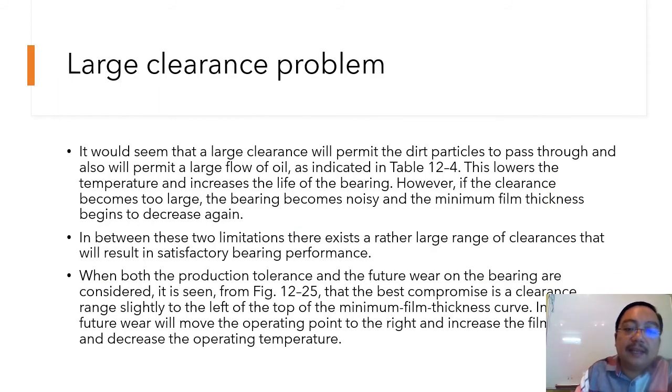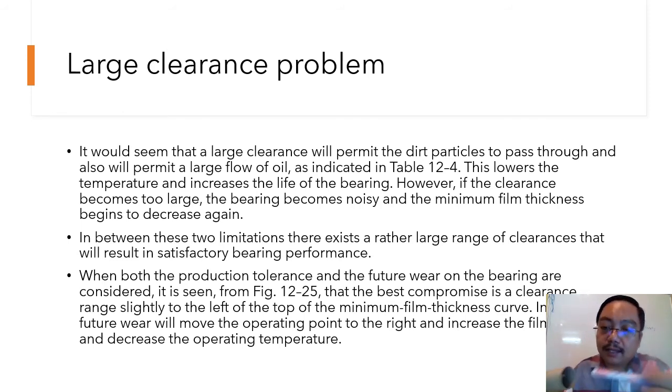And as I said, big clearance also gives a problem. Small clearance is also a problem. It seems that large clearance will permit particles to pass through and will permit large flow of oil, as indicated. Of course, lower the temperature, increase the life of the bearing. However, if clearance becomes too large, the bearing becomes noisy. This is logical because of the clearance.